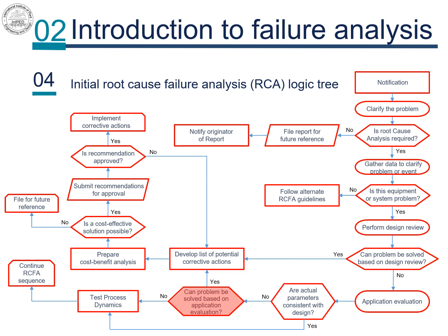No would mean again going to RCFA sequence, but yes would be a more desirable road towards developing corrective actions and performing a cost-benefit analysis. Out of which a question would arise, is cost-effective solution possible? And if it is, recommendations would be submitted for approval, based on which would proceed with the implementation of corrective actions. In the event of recommendations not being approved, the process would return to the reworking of the corrective actions. Also, if the solutions provided would not be cost-effective, the whole process would be filed and a search for cost-effective solution continued.